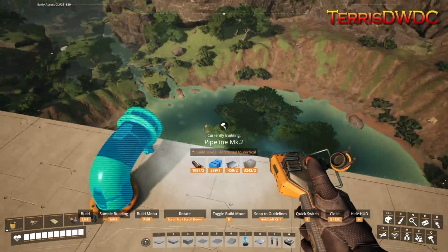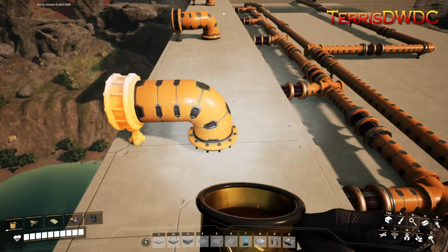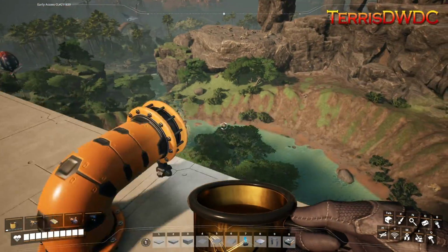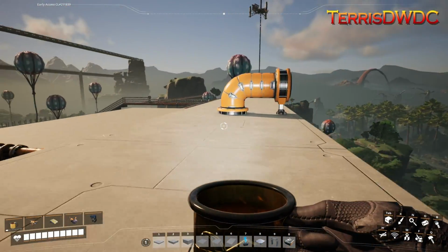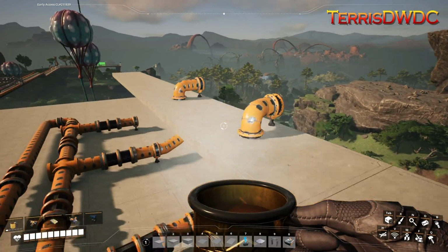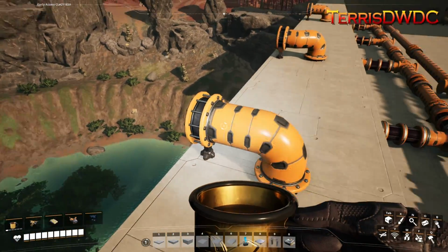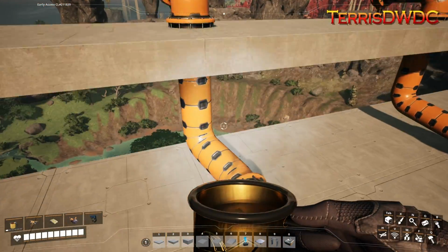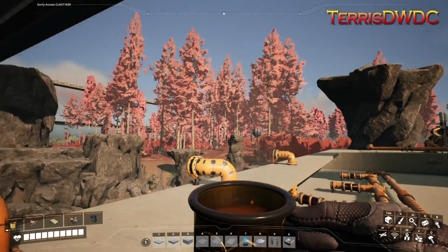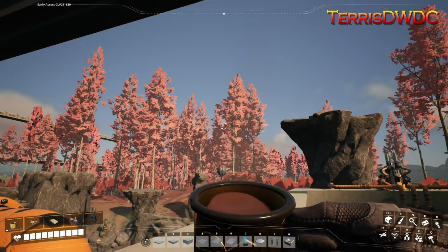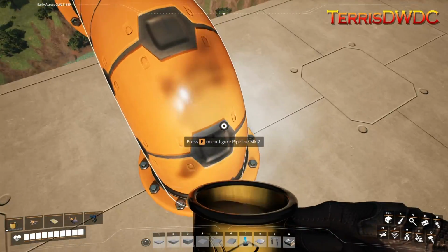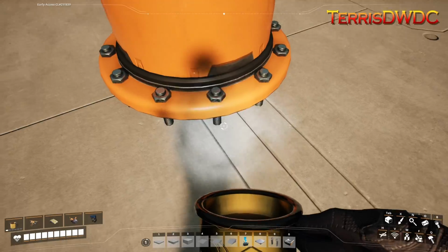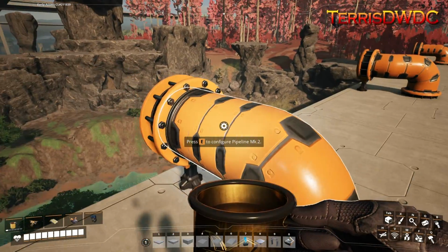so on and so forth along the way here. You've used these nice floor holes and everything's looking totally sharp and you're super impressed with how it looks. Save yourself the headache. Don't use the floor holes. I would say 30% of the floor holes that I laid out in my factory out there, for whatever silly reason, the fluid wouldn't go past it.